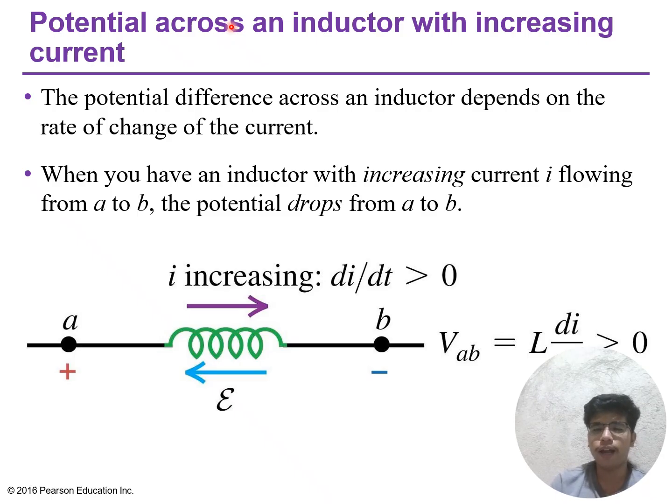So larger L slows the rise, larger R speeds it during the transient. Energy stored in the inductor grows. So we have U equals 1/2 L i squared. At steady state, as t goes to infinity, the current is constant, I equals V over R, V subscript L is equal to 0, where V subscript R is equal to V, and the stored energy is U equals 1/2 L (V over R) squared.